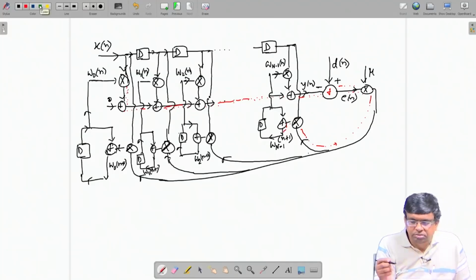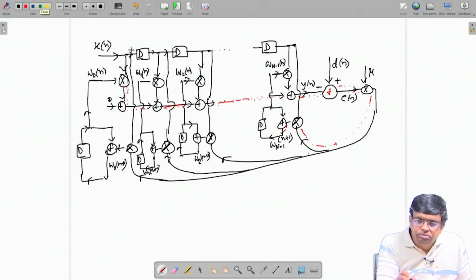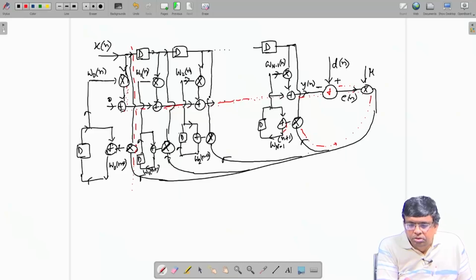Suppose I cut like this. So, this is one direction edge, this is one direction and this is reverse direction. I want to have a delay here. So, if I want to have a delay here, this will become D, this will become 2D because they are in the same direction, and from the opposite direction I should take out one delay. But is there any delay in this edge? No. So, it will become negative. So, I cannot do retiming.